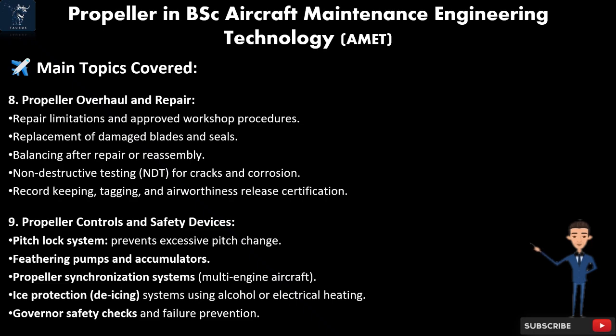9. Propeller controls and safety devices. Pitch lock system, prevents excessive pitch change. Feathering pumps and accumulators. Propeller synchronization systems for multi-engine aircraft. Ice protection, de-icing systems using alcohol or electrical heating. Governor safety checks and failure prevention.